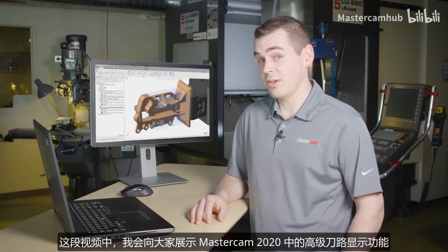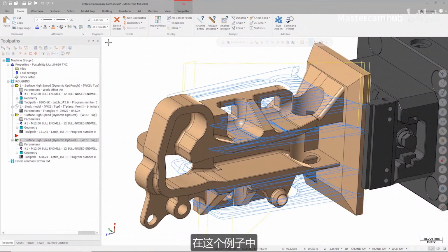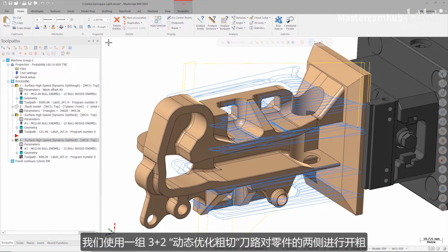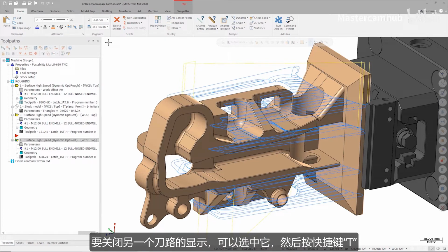Hi, I'm Jesse with Mastercam, and in this video I want to show you the advanced toolpath display functionality in Mastercam 2020. In this example, we have a pair of 3+2 dynamic OptiRest operations that are roughing both sides of this part. For now, we're going to focus on only one toolpath, so I'll turn off the display of the other toolpath by selecting it and hitting the T key on my keyboard.